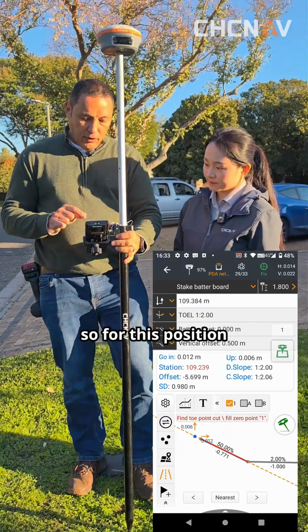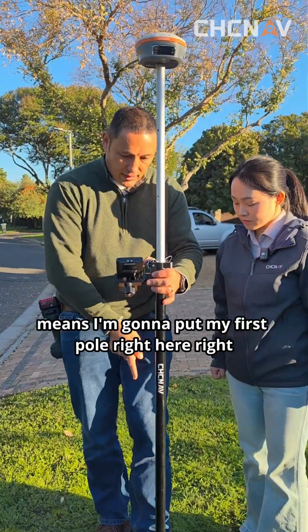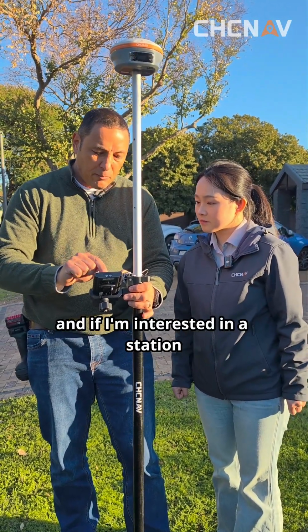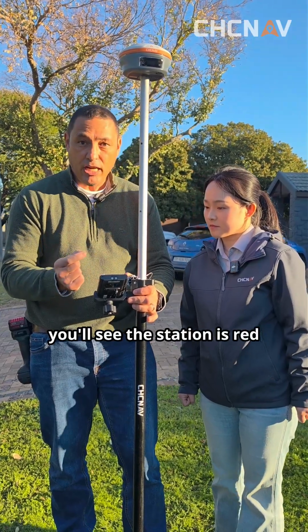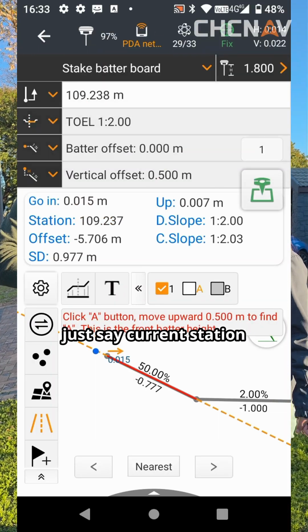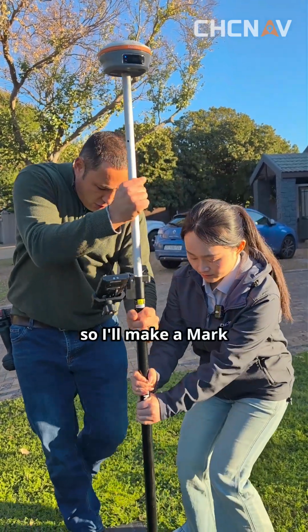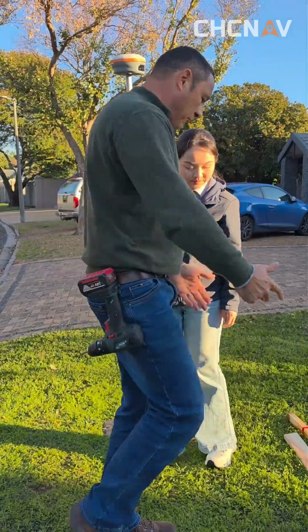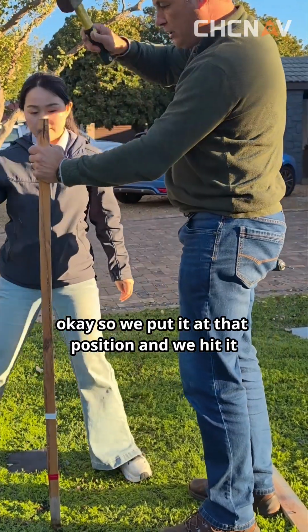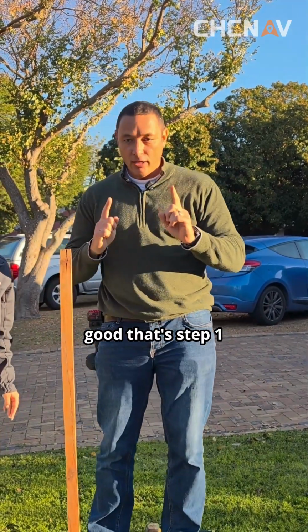All right. So for this position, there's no batter offset. It means I'm going to put my first pole right here. Right. So all I'm looking for now is go in and go up and down. And if I'm interested in a station, you'll see the station is red because I'm not on the station that I was on earlier. So I can say, no, stay on this station. Just say current station. And then the GPS gives me feedback. It says, you're at the right position. So I'll make a mark and I will get my plank and I will put in my batter plank. Okay, so we put it at that position and we hit it in the ground. Good, that's step one.